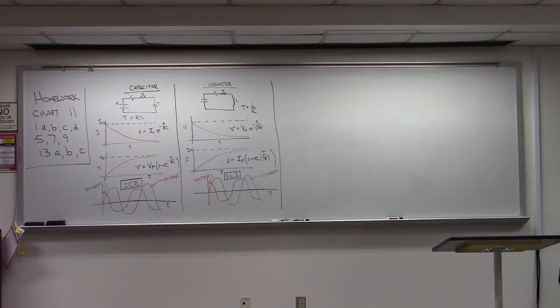And B is, C is 10. D is 100 millivolts. Okay, now we're measuring milliamps because of the clamp scale. What about the scale on your clamps? 1 millivolt per milliamp.